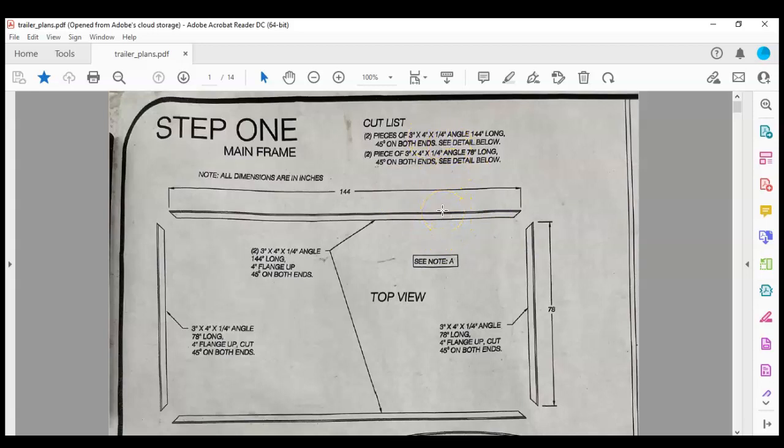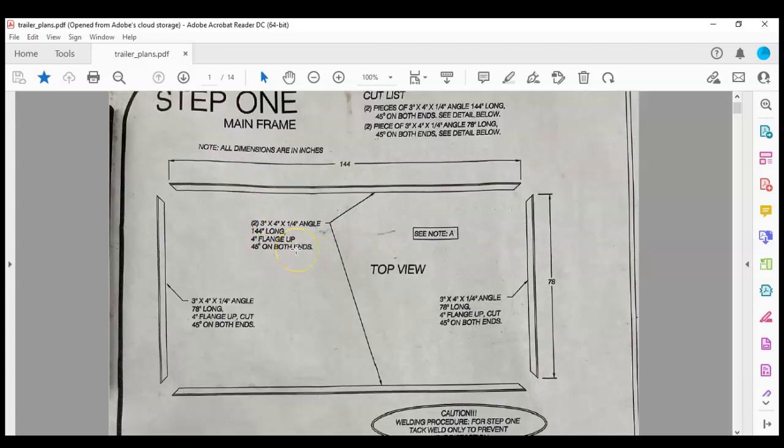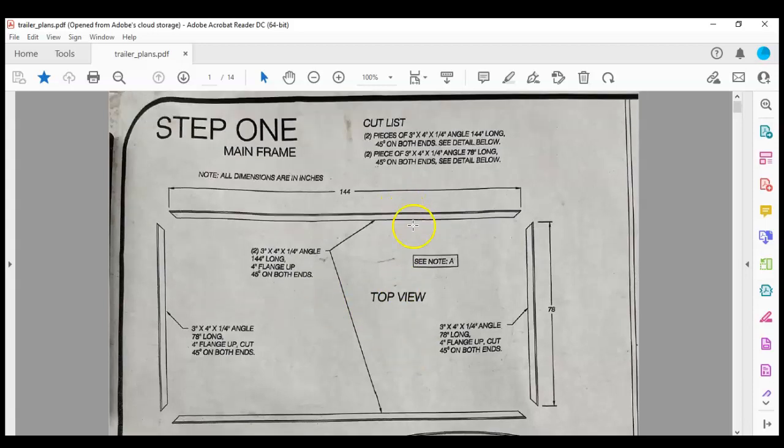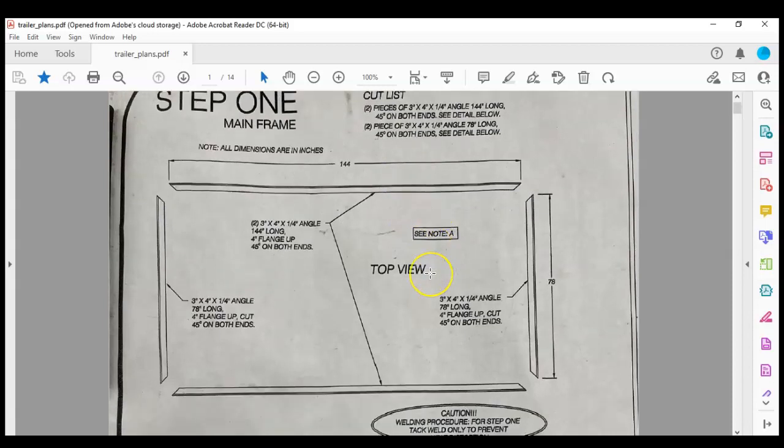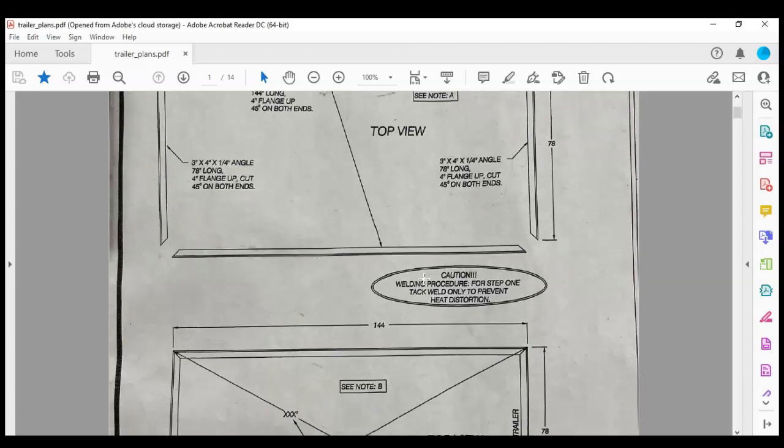And one thing I will be sure to say: Frame Generator is great for doing metal projects such as a trailer, where you're placing different items, different materials. It's not to take the place of other tools if you're wanting to do something wood or sheet metal or things like that. This is really for structural steel. And so I just want to clarify that real quick.